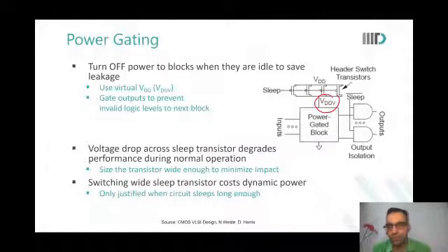Yes, that will come. But overall leakage will reduce, no? For our logic, the leakage will reduce, but there is the sub-threshold leakage of those PMOSes. So it is again the same thing. Look at it like this. There will be a KCL that will apply. If the power gated block does not allow sinking more current, how will more current go? It will not come. It will only be up to a certain limit.